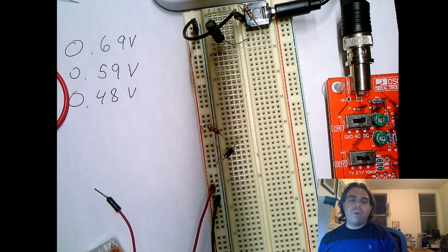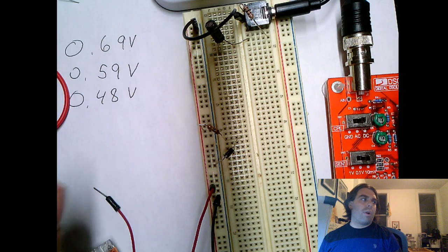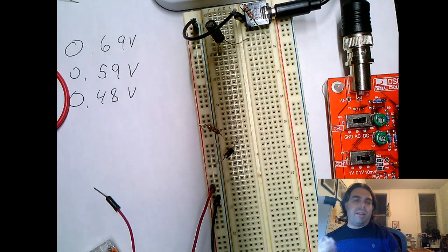drop across the diode. So diodes have a different kind of reaction to voltage than a resistor. They're not going to work as a resistor, as a resistor divider does. And so this is important because when we put them in our circuits, they're only going to consume like 0.4 to 0.6 of a volt, and it's going to be pretty consistent no matter what our voltage divider is.